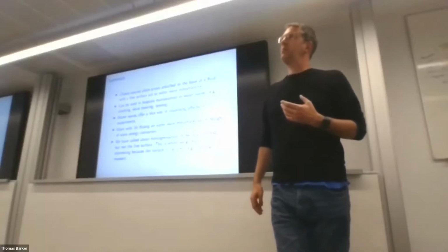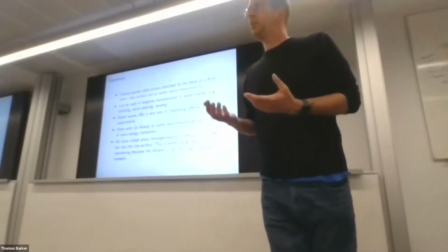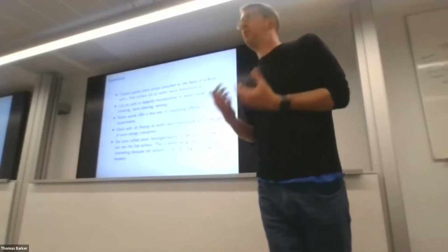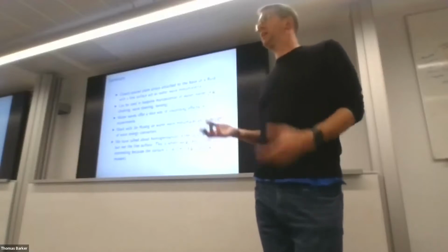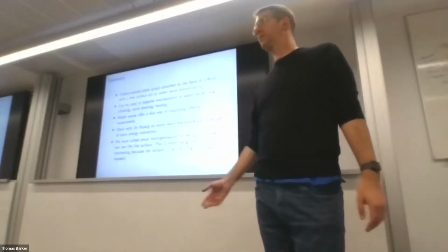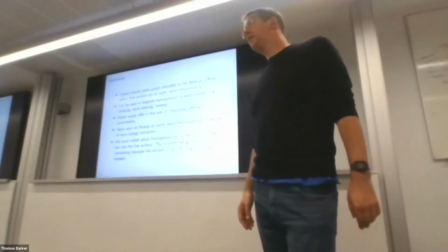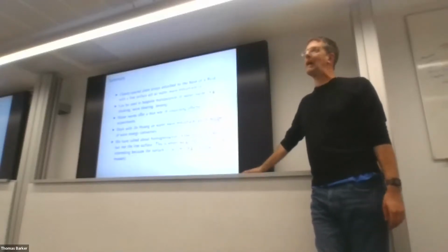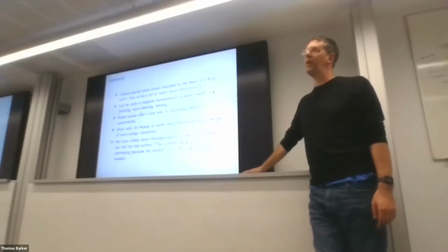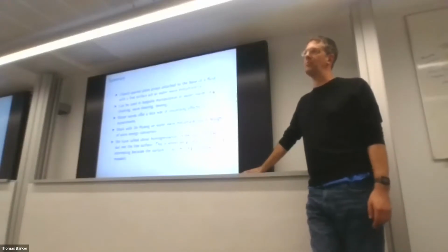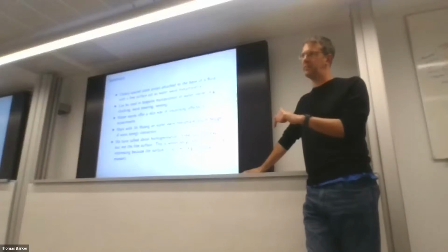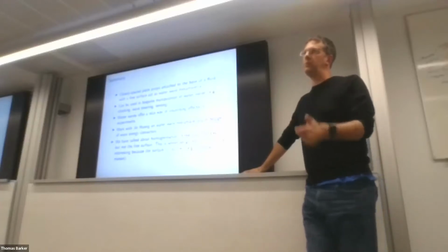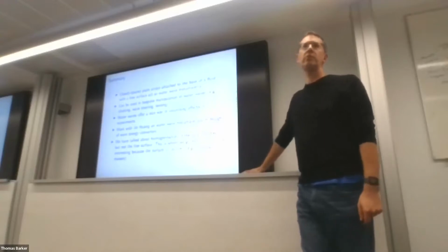As I say, we've added damping artificially to the cylinder and seen that there's a lot of power come out, but you need something which represents something that you would build physically. So we've imagined that that might be paddles in one instance, and that works basically just as well. It turns out it doesn't matter where the damping happens, as long as you've got some damping somewhere inside the cylinder, it will take out the power that's available. So that's one conclusion that we've drawn.